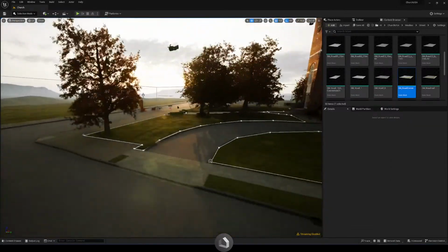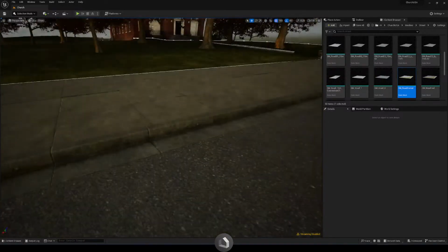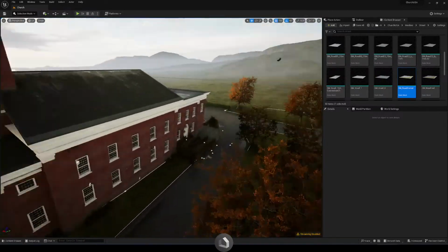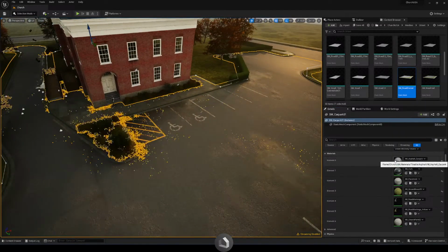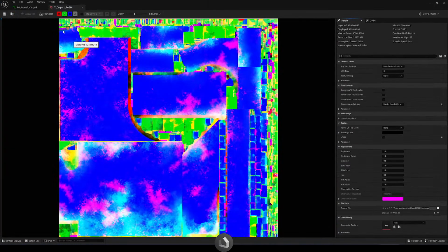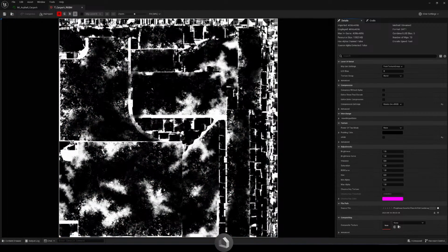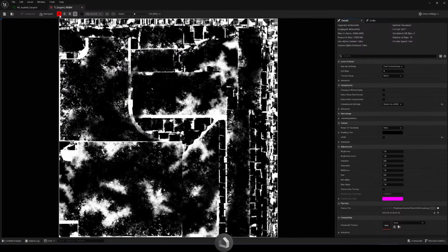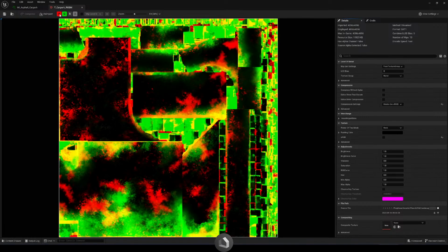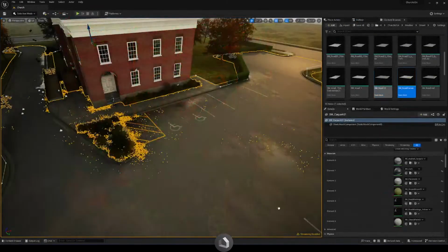Yeah, because I don't think you can use vertex painting with Nanite the way you want it to work. So I'm sort of scouting around that by using masks. I'm using an RGB mask for the road. So I believe that's the puddles. Or is that the puddles? I think that's the puddles. And then that's the cracks. And then I think that's just AO at the end. And that's mapped to a second UV. So UV1 is tiling, UV2 is this. And that defines all those.